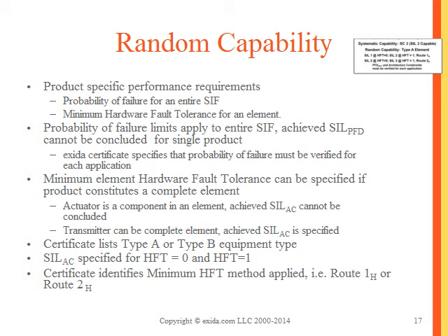When we look at a transmitter, it can be a complete element. In that case, we will specify an architecture constrained SIL level. So depending on the type of equipment, we can specify up to what SIL level a product can be used in.